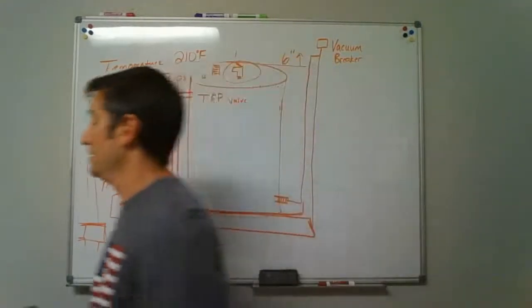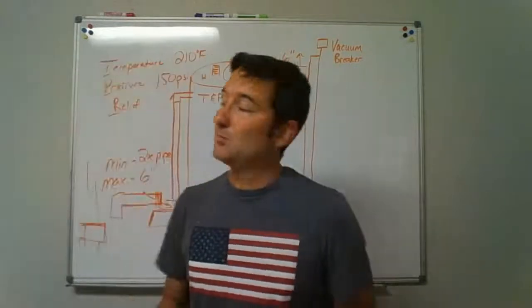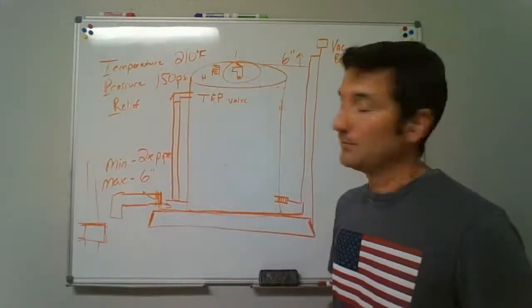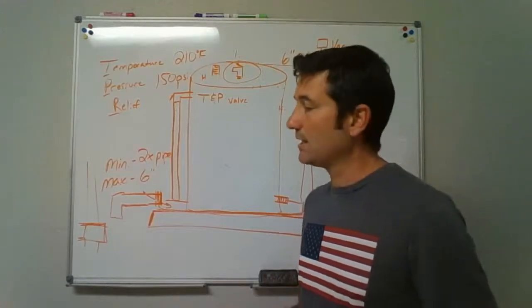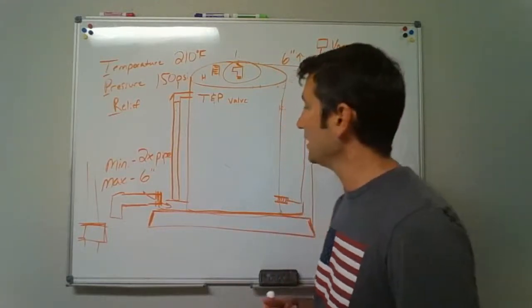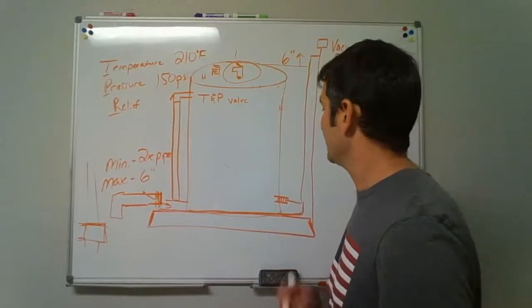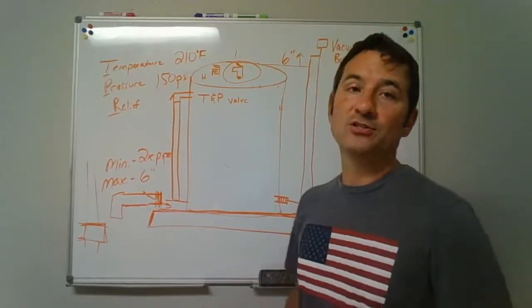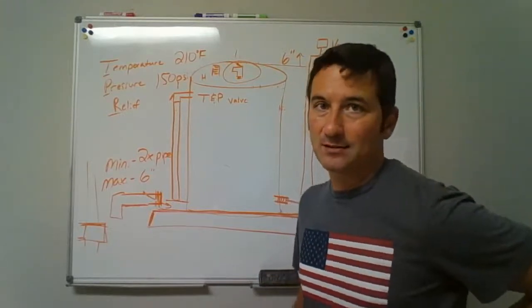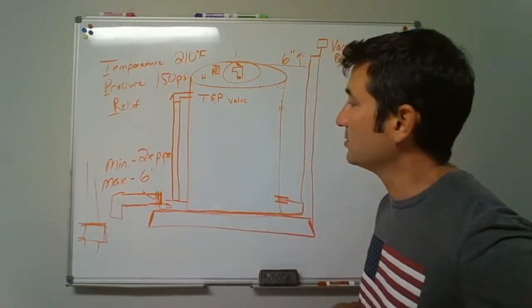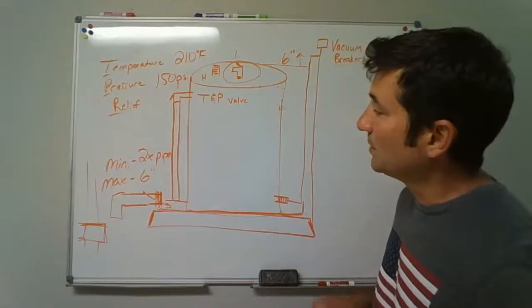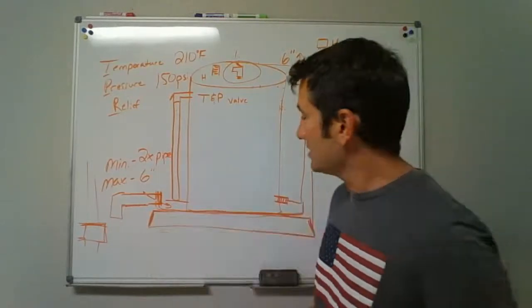So once again, they didn't have a pan on it before. Nah, you don't have to put a pan. Oh, well, they had a pan underneath it, but didn't put a pan drain. Well, where they didn't have the pan drain, you don't have to put a pan drain. But if we do install it and it's new, and it says we're supposed to put a pan on it and get this drain out, then that's what we need to do. It gives you some locations.